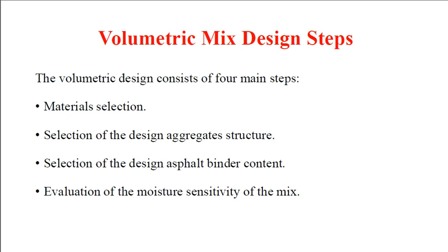Now the volumetric mix design steps. The volumetric design consists of 4 main steps. First is the material selection. Second, the selection of the design aggregate structure. Third, selection of the design asphalt binder content. And fourth is the evaluation of the moisture sensitivity of the mix.